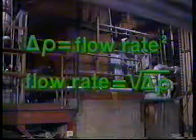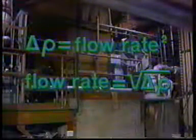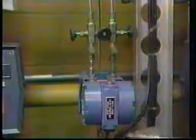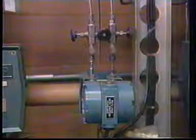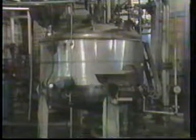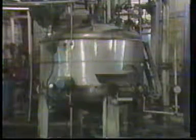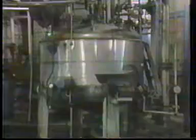A formula derived from a volume flow equation can be used to calculate the flow rate directly from the differential pressure. The fact that differential pressure can be readily and accurately measured by means of a variety of devices makes this principle suitable for practical application to flow measurement. To illustrate the principle, we've been using an incompressible fluid. However, Bernoulli's law applies to both liquids and gases. When measuring gases, though, it's necessary to account for changes in density. A factor must also be included to correct for energy loss from friction.